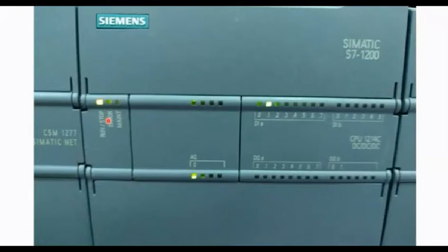In previous PLCs this option was not available, you needed to check it. And there was one switch for on/off for maintenance, but in the latest one, this S7-1200 and 1500, there is no option for the switches. You can configure it directly through your system, no need to change a hard switch on the PLC. So here you have only LEDs showing that you are running right now, or you are in maintenance condition, or you have any error. So it is easy compared to the previous one.